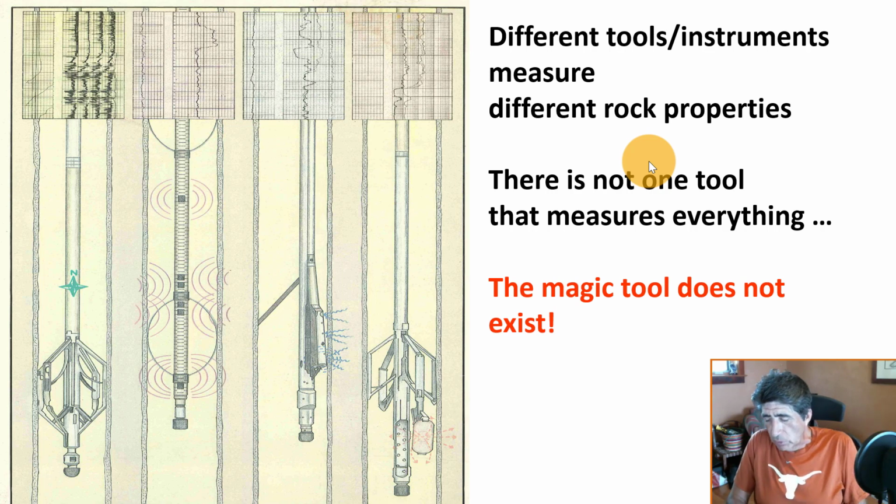The other thing that is very important to remember in the context of samples of rocks that are acquired here is that very often the drilling process itself also produces cuttings of rocks. We call these rock cuttings or drilling cuttings. And those are sent with the mud back to the surface and they're collected. So that's another way to sense the rock properties, although not very reliable because these are fragments of rocks that were crushed because of the drilling process, or maybe they have some value, but they do not represent in situ properties.